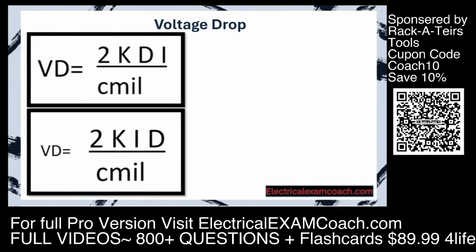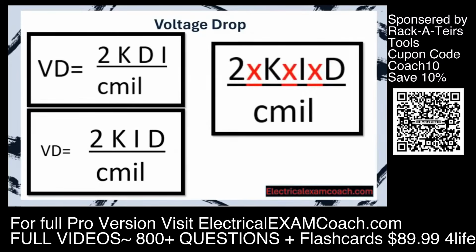I do it like this: 2 kid over C mil. Easy to remember and easy to plug in. And what this is, just like previously in the program, this is implied multiplication. So it's going to be 2 multiplied by K, multiplied by I, multiplied by D, divided by C mils.